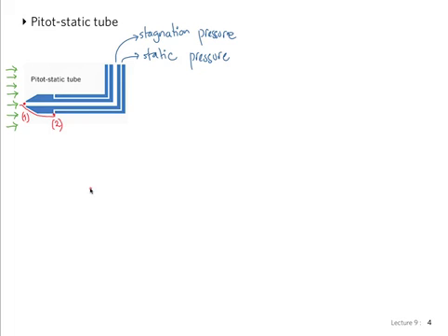So it's a streamline that is passing through points 1 and 2. Because the flow is continuous, I'm looking at one streamline just right next to the pitot tube, and I'm going to be content with the approximation that it is right next to the stagnation point so I can apply Bernoulli.